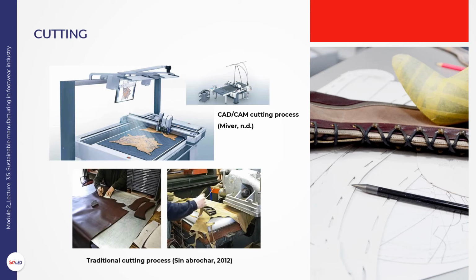The relationship between investment cost, operating cost, speed and flexibility that these systems offer compared to traditional die cutting must be calculated. Most CAM systems allow simultaneous marking, numbering, and punching of parts. When comparing the return on investment of a traditional cutting machine and a CAM machine, the possibility of grouping the operations mentioned above and the optimized use of the material to be cut should be taken into account.